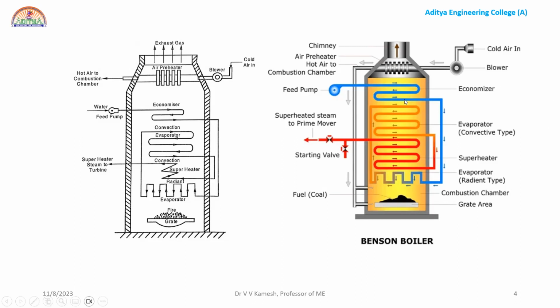First at the economizer level, light. And next in the radiant evaporator at the high side, again in the convective evaporator at the medium side, and again in the superheater, somewhat more than average. Okay. So these red color pipes contain steam at high pressure, because even in the radiant evaporator at the bottom side, much of the water will be converted to steam.